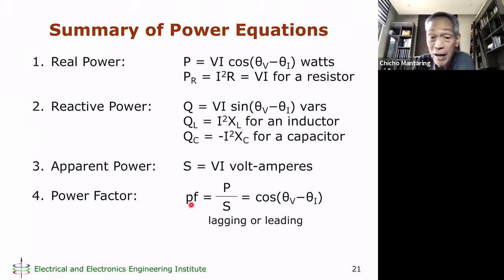The maximum power factor is 1. If the power factor is 1, you have a resistive circuit and your reactive power is equal to 0. As your power factor gets lower, your reactive power gets higher. Meralco will charge you, for example, a penalty if you exceed or if you go below a certain power factor. So that is how we are billed electrically in our homes.